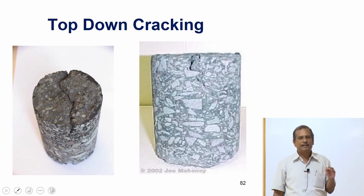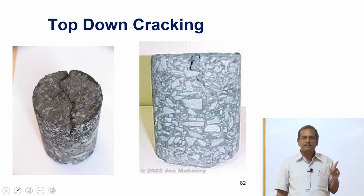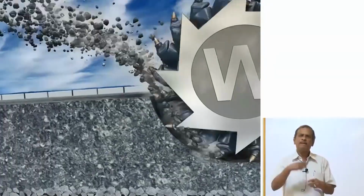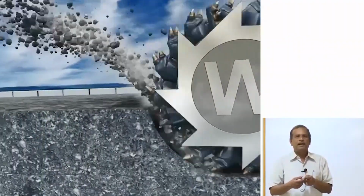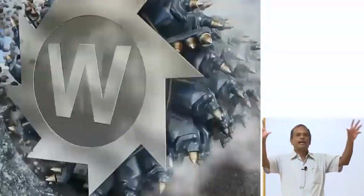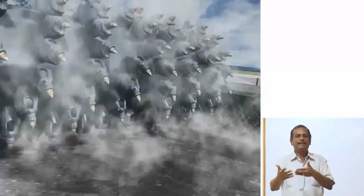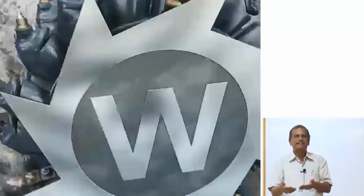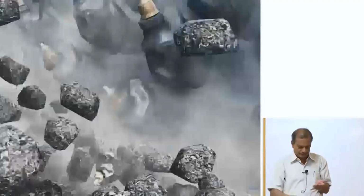In a nutshell, sustainability talks about reduce, reuse and recycle. It's time that you adopt recycling technologies in road construction. So, if you look at this, I can mill the entire material. Now, milling machines are available. If the road has deteriorated, I need not provide an overlay. You mill the material and use the material again and again. So, milling is the first step when you want to reuse the materials.